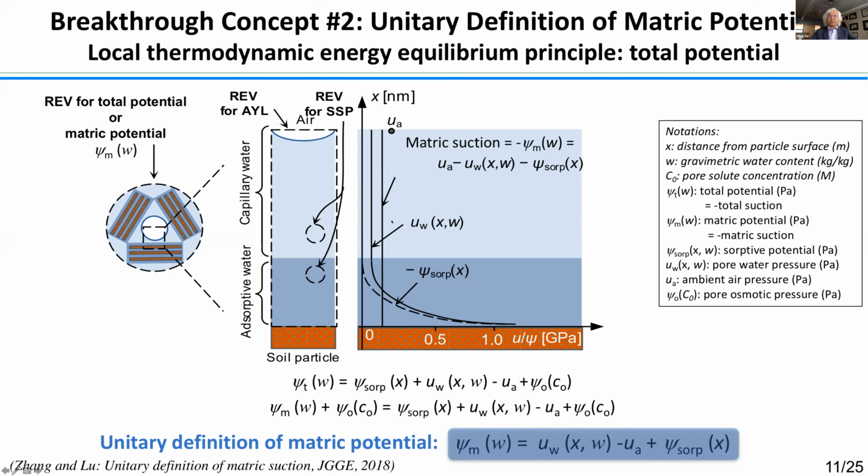Now, under that condition, this equation simply states that you're going to maintain your pore pressure negative all the way until some point where you're close to the absorption field, the electromagnetic field, where the water molecule is going to interact with your soil particle.